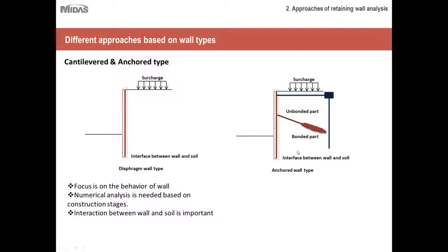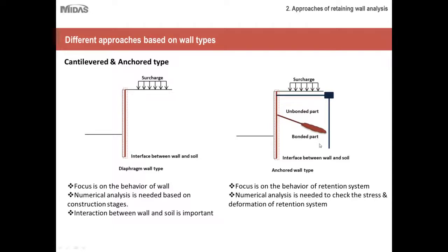So depending upon what type of retention system you are using, you should model that accordingly. But from this slide I want you to understand that for anchored wall type, the prime focus is not on the wall alone, it is on the retention system that you are using. And therefore numerical analysis is needed to check the stress and the deformation in these retention systems.